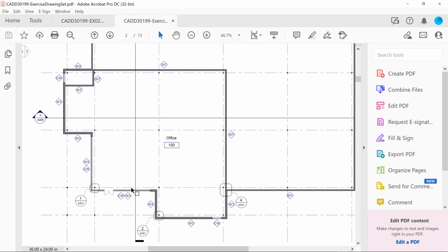Now here, it's still a W3 wall with a curtain wall inserted. Then it stops at this point. Now, notice that there is an offset distance from the grid to the wall. So I'm going to place a 1 meter offset. Now, use a different value. Okay? I'm just going to demonstrate a 1 meter offset from the grid.